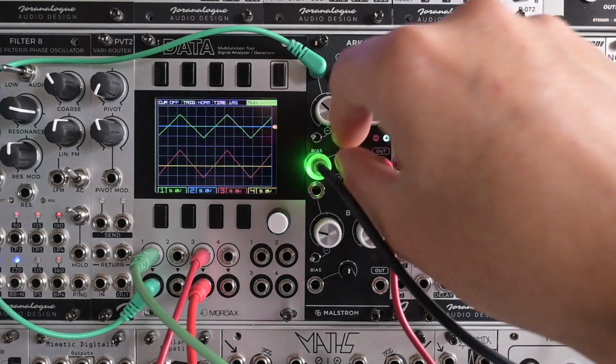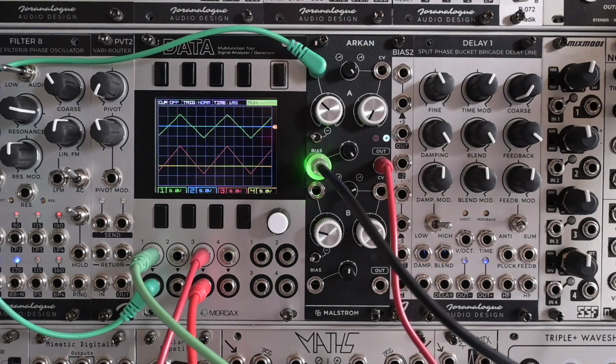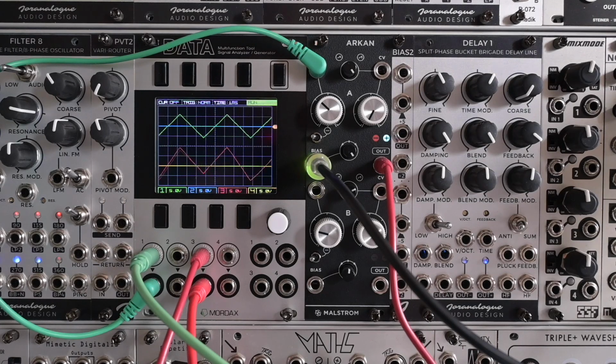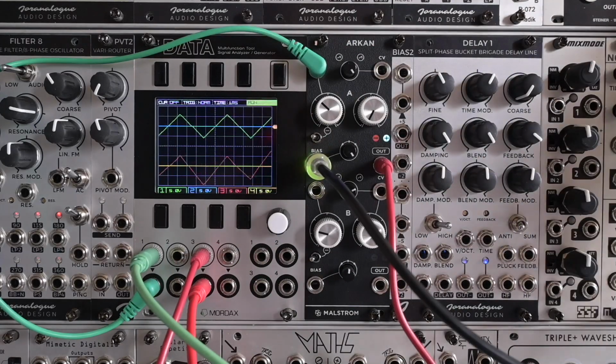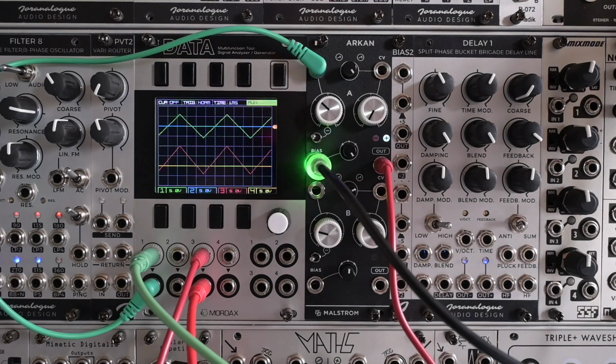Like that. Now you can also hear that this doesn't change the sound even when I turn up the speed. Well, if you're using a headphone or good speakers, at this point you might be starting to hear an extra frequency being added to the sound. And what we're doing here is actually just mixing in a second VCO, or when you slow it down, you're kind of mixing in a second LFO, and this is causing the offset to happen.